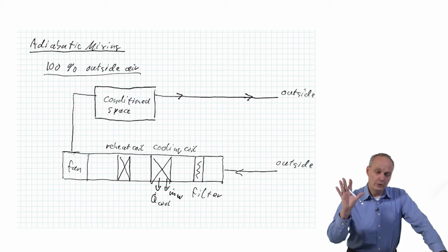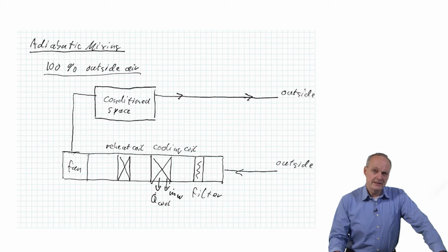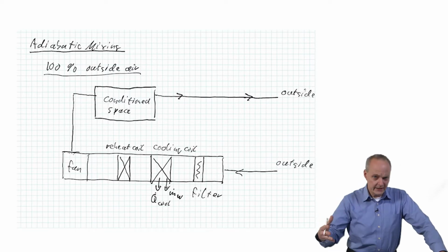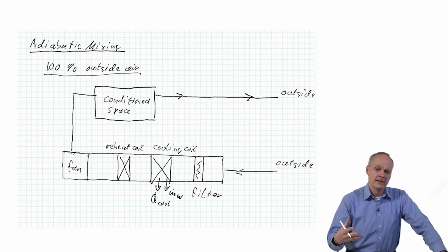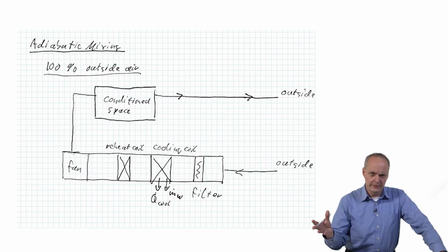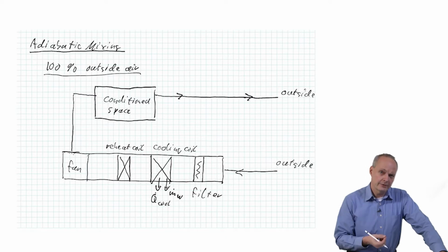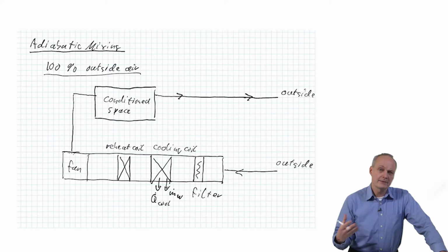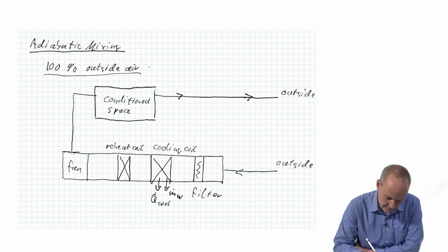There, everything north of the corridor is laboratory space. And in these spaces, you do not want to take air from one lab into another lab, because if you have something like a chemical spill, then you don't want to take contaminated air and distribute it all through the building. So code requires that for situations like laboratories, hospital operating rooms, clean rooms, you have 100% outside air, okay? So required by code